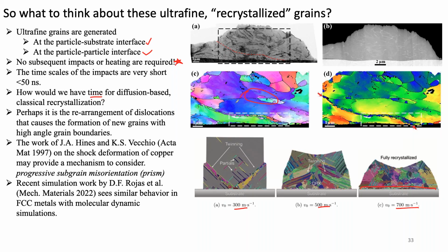Ironically, early on, cold spray was very attractive in part because of its limited thermal heat input. Now you're actually increasing the thermal heat input. It's really all about control. One of the biggest areas we're working on actively in my group is understanding and controlling the heat transfer process during laser assisted cold spray, because you can in fact get carried away for sure.